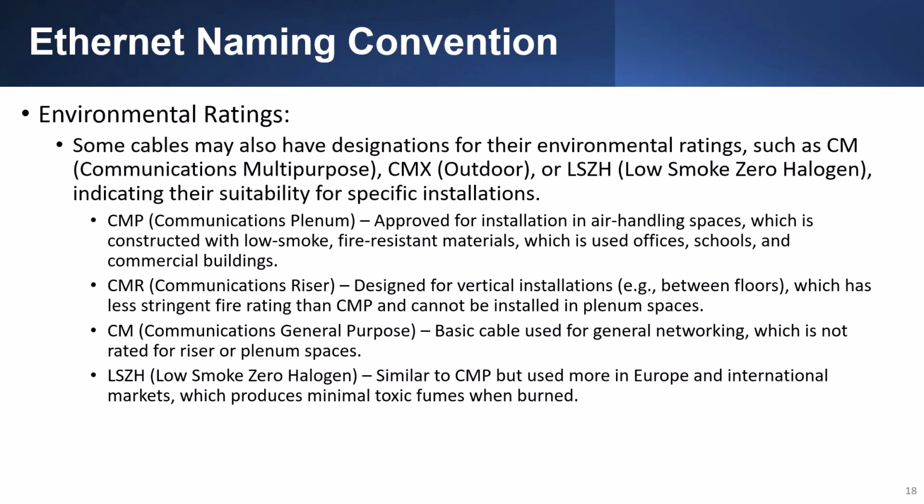Communications riser, or CMR, is designed for vertical installations between floors, which has less stringent fire ratings than CMP and cannot be installed in plenum spaces. Communications general purpose, or CM, is basic cable used for general networking, which is not rated for riser or plenum spaces. Low smoke zero halogen, or LSZH, is similar to CMP, but is used more in Europe and international markets, which produces minimum toxic fumes when burned.